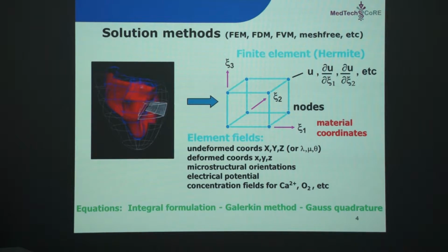In the soft tissue mechanics sense, and the work with the heart, we often use finite element methods, 3D finite element methods with anisotropic material properties, because we've got different stiffnesses in the different directions. And so we use finite element methods to do that based upon a Lagrangian approach where we can deal with microstructural material coordinates and in 3 dimensions, in different types of coordinate systems. So we can use those coordinate systems to represent the different fields and the different quantities of interest numerically, so that we can solve these things on computers.